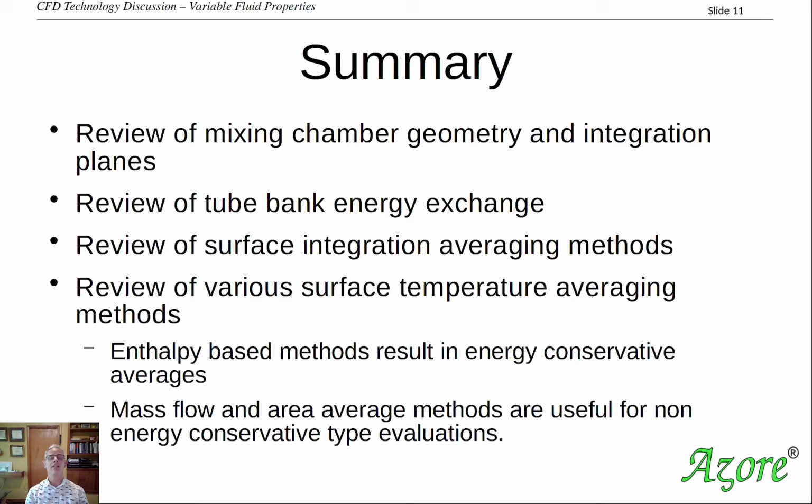And then we looked at a number of different surface integration methods. We looked at an energy conservative surface integration technique, a mass weighted temperature, and an area weighted temperature, and we reviewed the differences we observed in this particular test case.